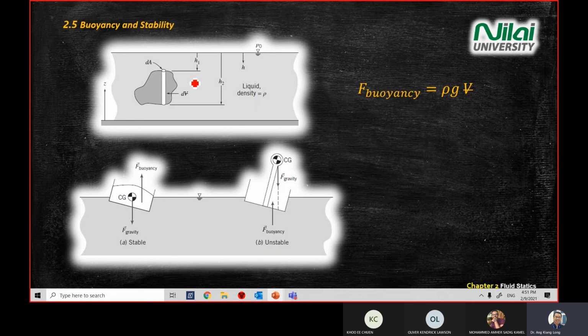If you have hydrostatic problems, then the object will be slanted at a certain degree. Hydrostatic will be rho gh or P0 plus rho gh, depending on the question itself. But when you talk about stability, it will link up with your center of gravity. So if you're given an object like you see on the second diagram here on the left hand side, why does the diagram say it is stable?